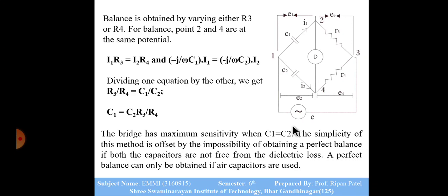The simplicity of the method is offset by the impossibility of obtaining a perfect balance if both the capacitors are not free from dielectric losses. A perfect balance can be obtained if an air capacitor is used.